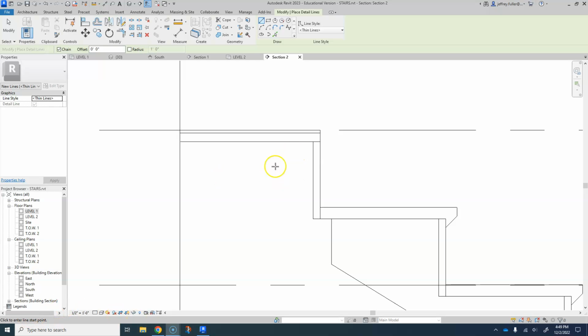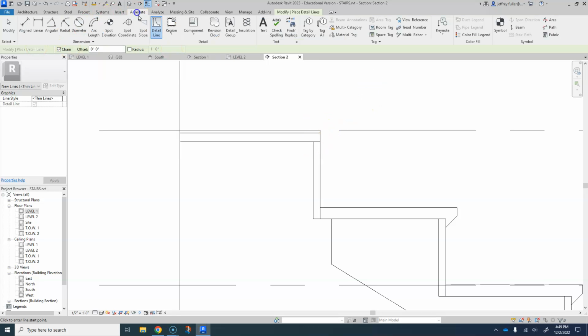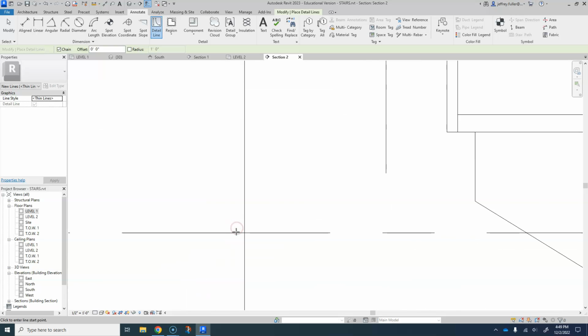Okay, so I'm back, and now I'm going to draw that floor joist in here. I need a line. Okay, so I'm going to draw over this way 3.5 inches because it's made out of 2x4s. I'm not going to draw all the way down to the bottom because I forgot I got to put some drywall down there. So let's put a piece of drywall down there. This is our ceiling height right here.